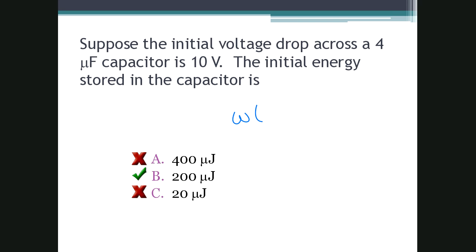So we know the energy is equal to, I'm going to write this a little slower so it looks nicer, W of t is equal to 1/2, and we're looking for energy input, okay? C, and we're given capacitance, times V of t squared. Dang it, it's supposed to be F. Right? So we're given the value for capacitance, we're given the value for voltage, and that's basically all we need here to find W of t. You plug those numbers in and practice doing this in your calculator, you should end up with, let me do green to make sure that you can see this in good color.